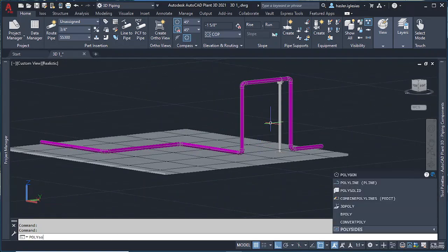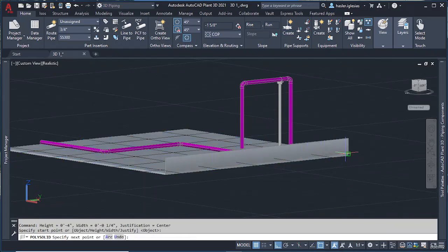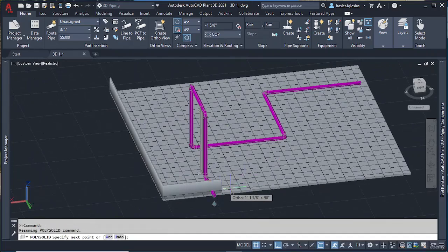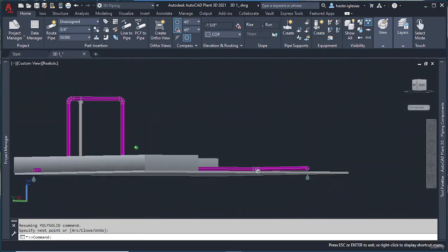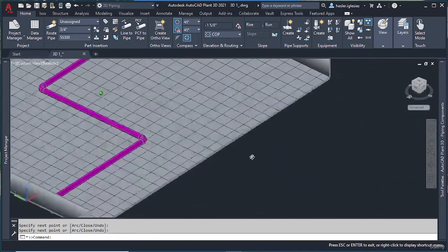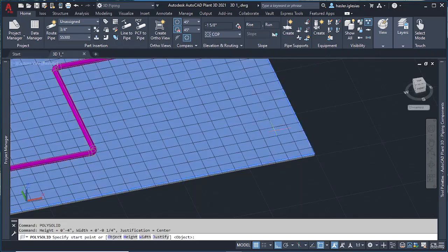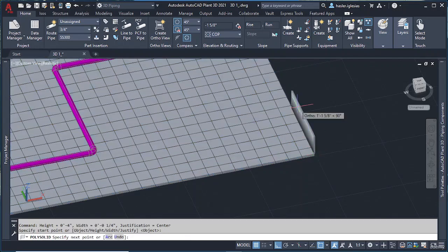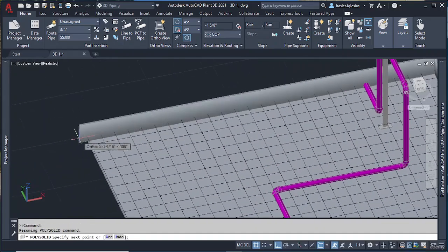Also, let's try how high a polysolid is here. Well, I can add this kind of fence, okay? I'm drawing kind of a closed garden. This is polysolid, remember, which is like this wall-like. Oh, let's go again. I pressed escape, and with escape it doesn't work. You have to click enter after drawing it, okay?